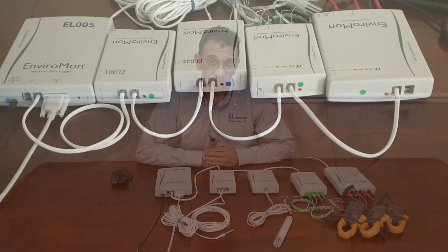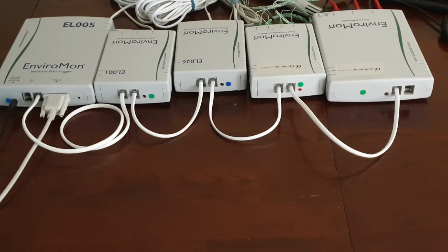Now, there are a number of ways of identifying where a network cable problem is. You can do this by looking at the LEDs on the converters, and as we said, it should be flashing every now and then. So you can go down the system and look at the converters and see which ones are not exhibiting the correct behavior. Then look at the converter cables that are connecting them. So I've grouped the converters together so we can have a look at the LEDs to see how they can help us identify where the problem with the EnviroMon network cable is.